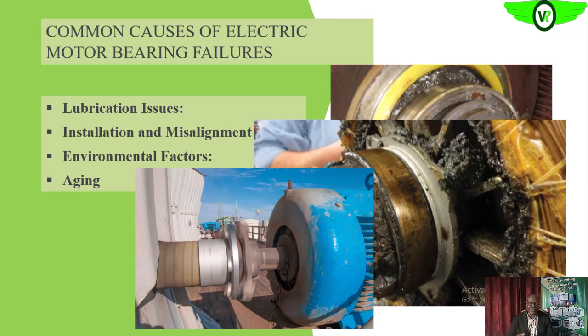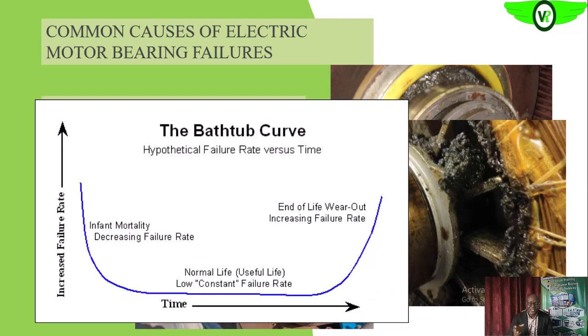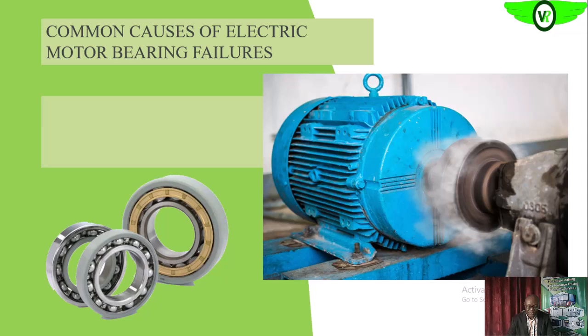If you are familiar with the bathtub curve, you'll see that a harsh operating environment will drive it into the old age region of the bathtub curve, where the probability of failure is usually very high. So those are some of the causes of bearing failure.